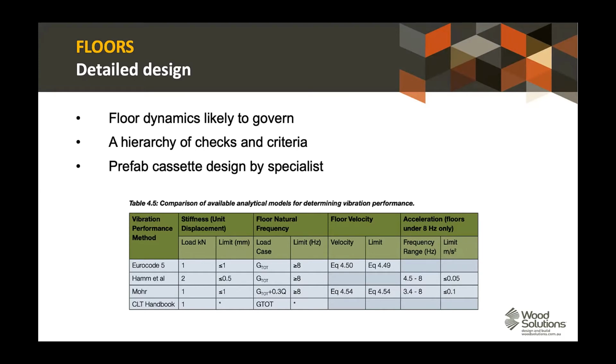So usefully, the detailed design from a prefabricated cassette solution is likely to be by the specialist fabricator. But that doesn't mean as an engineer that we shouldn't have a very, very good idea about what we're expecting in terms of member size and distribution of members before it then goes to that specialist for detailed design.